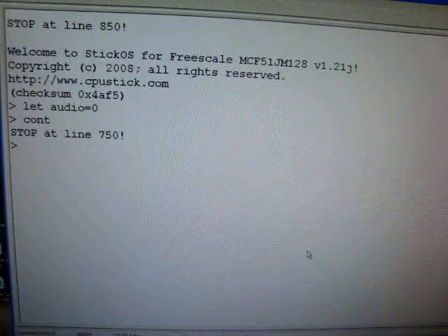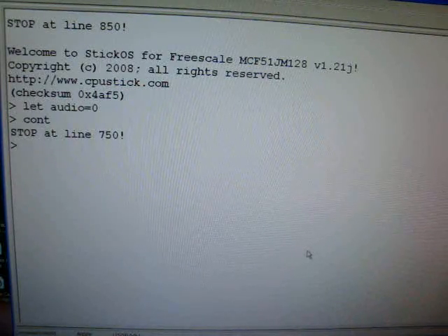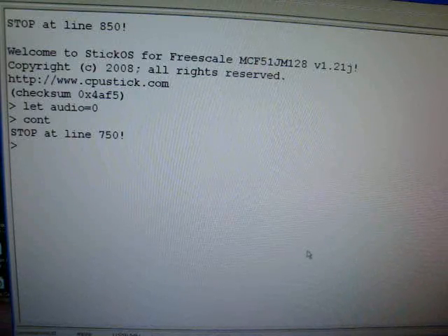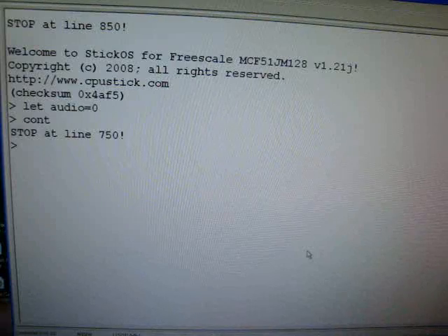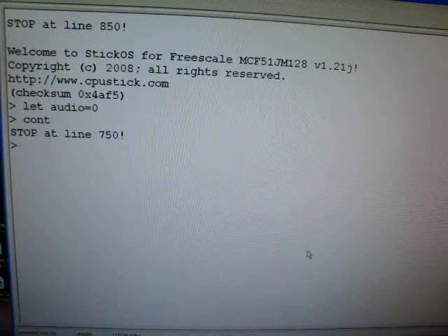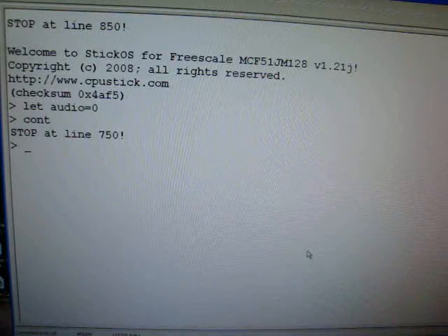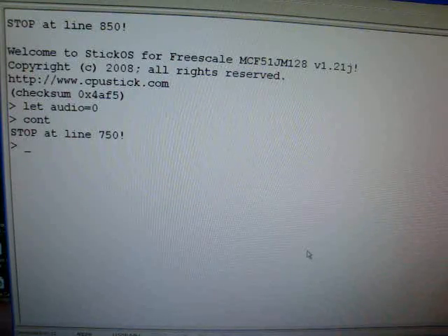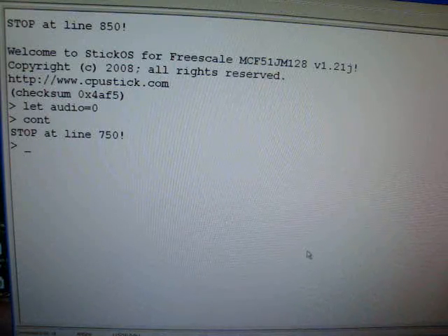Basically, we are in an interactive debug session where we have full control over the MCU. We came in through either 3 USB wires or some Ethernet wires or some Zigbee or whatever, and we've got full control over the MCU, just as if we were using an in-circuit emulator. We can stop the program, start the program, change the program. We can actually modify lines of the program, and we support edit and continue. So lines get recompiled, reintegrated into the program, and you can continue the changed program from where you left off.